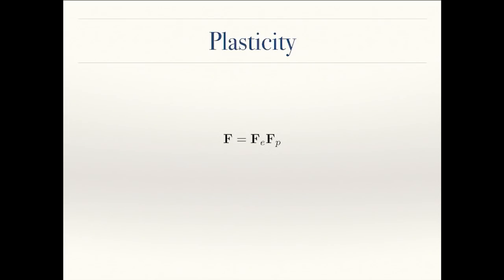The basic idea here is that we break our deformation gradient F up into two pieces. The elastic part, Fe, will determine what our elastic forces are, and then Fp, the plastic part. Fp models the permanent deformation that's happened, usually because something has failed in the system. And this won't be undone. It's actually changing the rest shape. So Fp is modeling how the rest shape is changing based on this plastic deformation. And then I'll turn it back over to Tamar, who will tell you about fluids.